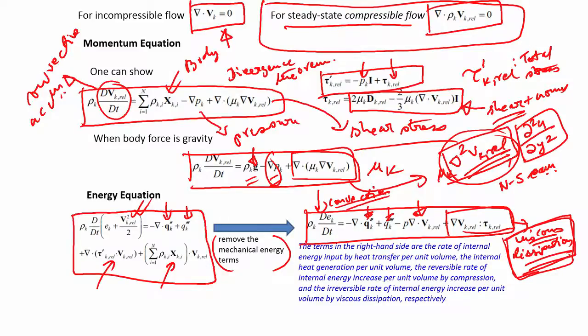This is the change of velocity with some distance. If this distance is very small and the change of velocity is high, you can generate a lot of shear. If you generate a lot of shear, your viscous dissipation can be a lot higher as well. So, the work done by viscous dissipation can be high. This can become a formidable component, as in the example that I showed you with my finger, but do not try this experiment, you will actually burn your finger.